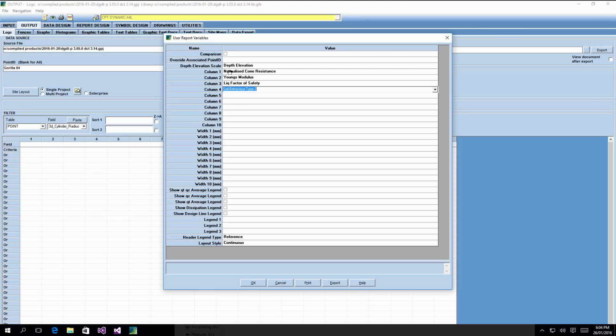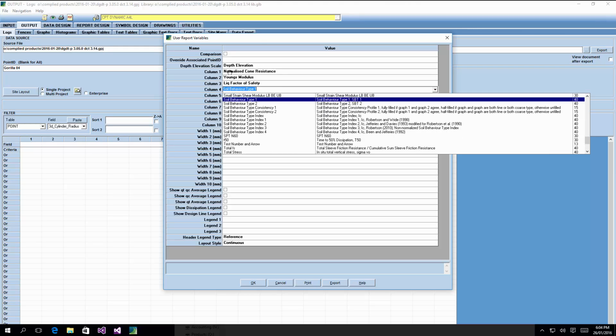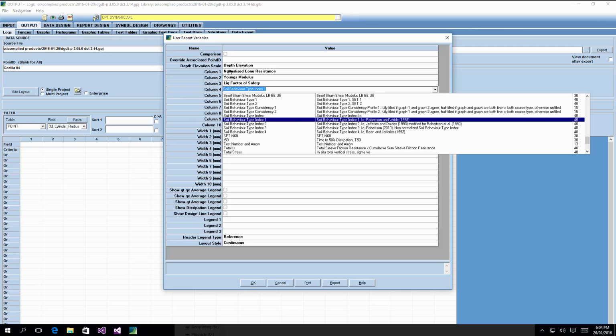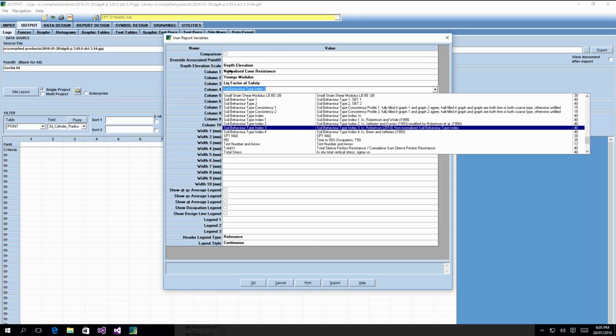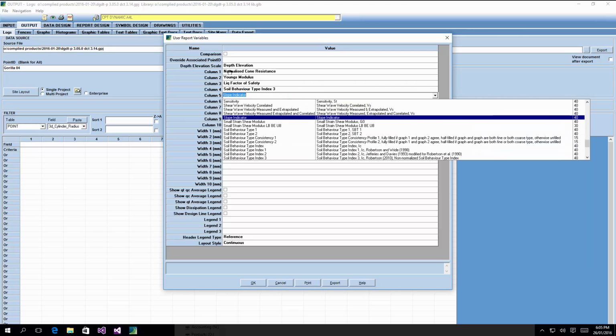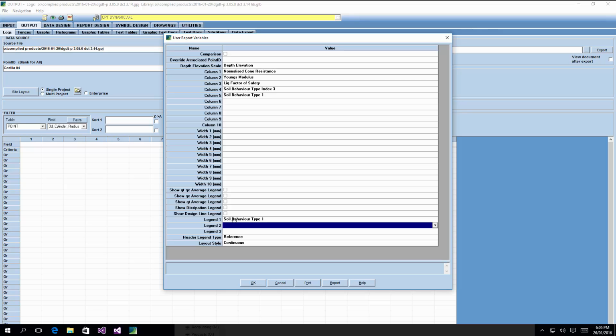Soil behavior type. Now we've got, with soil behavior type, the graph type approaches, which are these ones here. We also have the soil behavior type indexes. So many people seem to like this one, and well, there are other options. I'll show you that. So there are two graph approaches getting calculated, and all of the indexes are calculated at the same time, and you can display the legend down the bottom. So click OK.